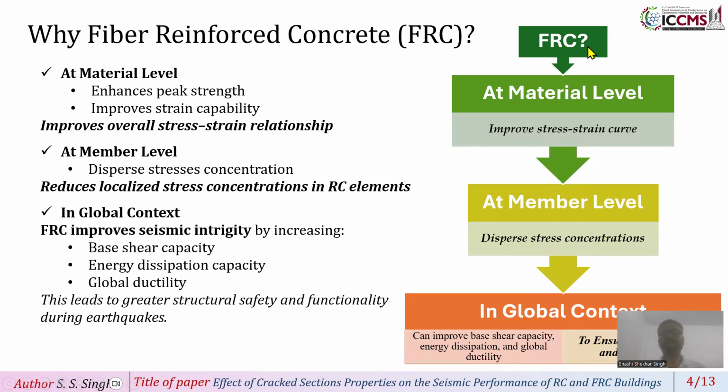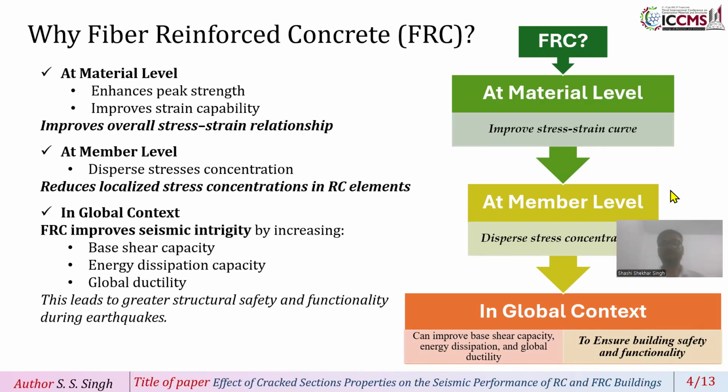Then why FRC? What is the meaning of FRC? First, we have to understand that FRC is fiber-reinforced concrete. It means fiber has been incorporated in the concrete matrix, and because of that, at the material level, it improves the stress-strain curve, and it disperses the stress concentration throughout the member. Because of that, in the global context, it can improve the base shear capacity, energy dissipation, and global ductility, and it will ensure the building's safety and functionality.